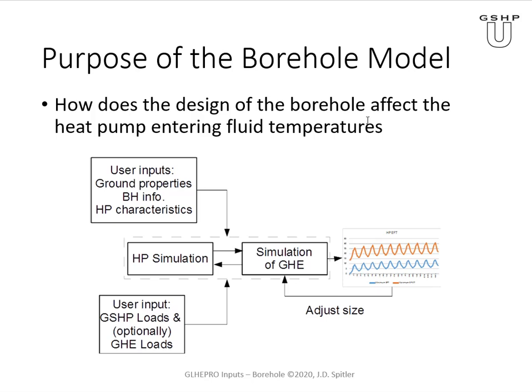Okay, so the goal here is to look at how the design of the borehole affects the heat pump entering fluid temperatures. Right, that's part of our sizing procedure. So this simulation, and particularly these temperatures, are affected by the design of the borehole. If we use thermally enhanced grout, these temperatures won't rise as high as they would with regular grout. That's what we'll be looking at.